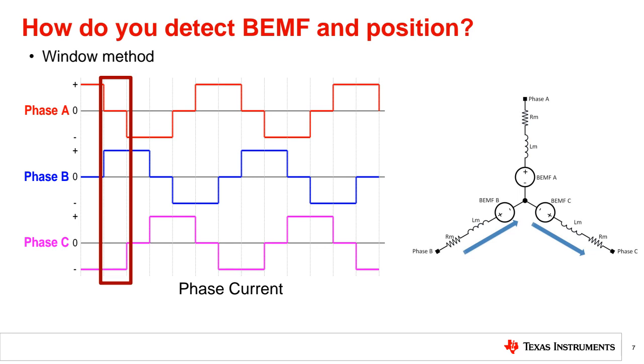Okay. Now we are installing a circuit. My maximum voltage level is 100. 100 means 3.3 in your microcontroller. Okay. If you read 3.3 volt in your ADC channel, the microcontroller will understand it: I am reading 3.3 volt.